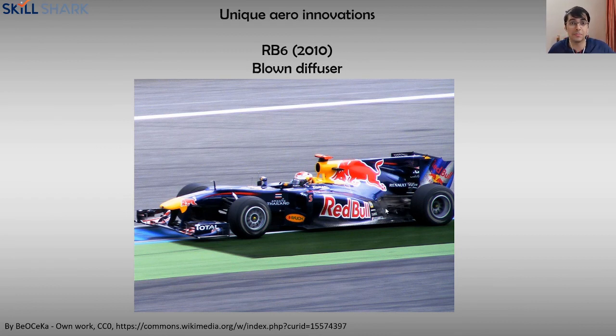So the rear tires are constantly spinning, so there's a lot of air that's being generated, vortexes and turbulent air that's being sent out from beneath the rear tires. And also when the tire goes on the ground, it squashes air underneath it and sends it out, so there's a lot of turbulence there. What happens is that ends up affecting the diffuser, because you want a good controlled environment behind the diffuser in order to make sure the expansion is also smooth. So what the blown diffuser does is it actually sends hot air to the sides of the diffuser between the tires and the diffuser, and creates this sort of channel, preventing any turbulent air from the rear tires to leak into that zone. That actually improves the diffuser's performance.